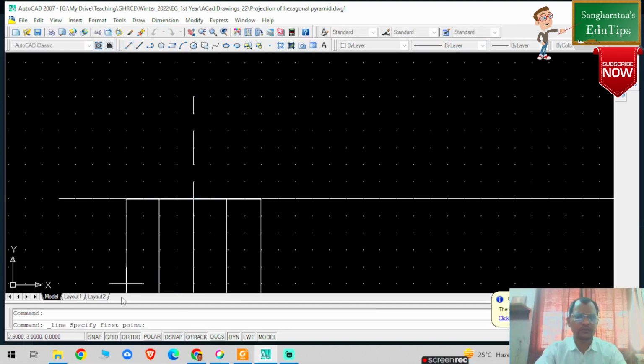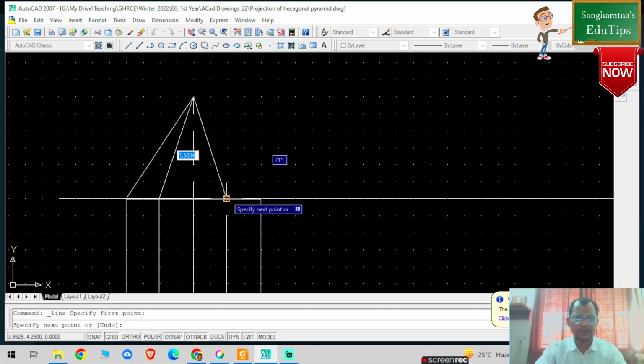Further, I'm going to unclick ortho and join all these projectors to the pyramid lines. From here as well it is going to be joined here. From this point it is going to be joined here, and from this point it is going to join here.